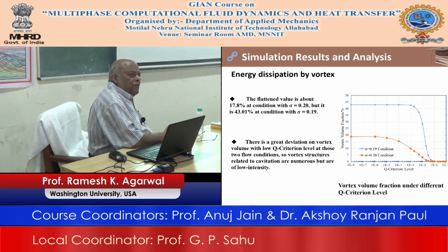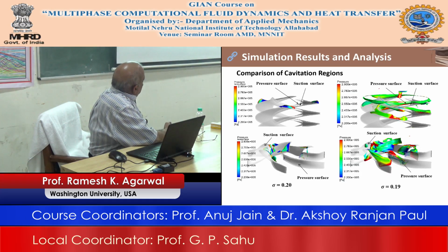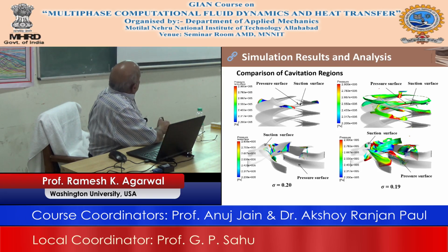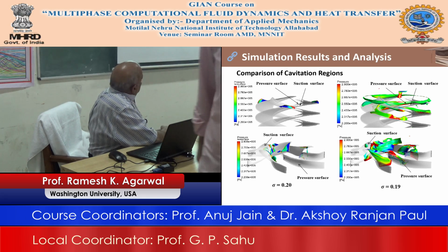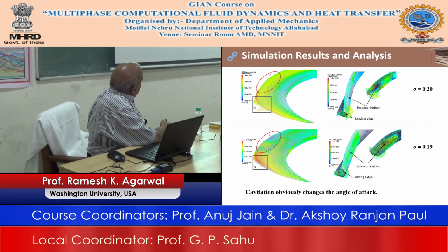So how do you classify those vortices? People came up in 2010 with what is called the Q criterion. This criterion defines a vortex as a connected fluid region with a positive second invariant of delta U, the gradient of U. So this is defined in terms of the velocity gradient.